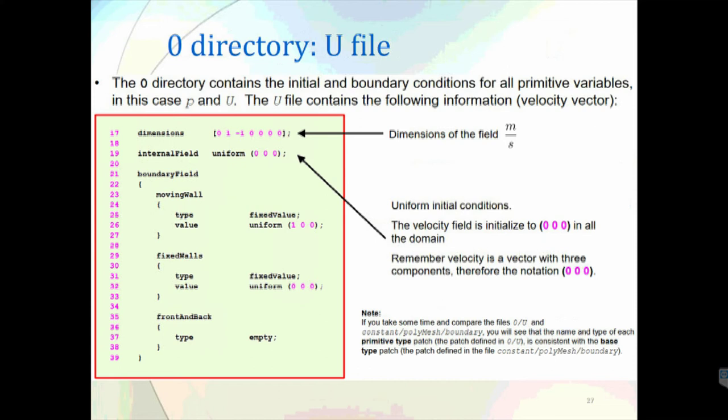Now this is the value of the boundary condition we want to specify. The value of the boundary condition was not specified in the earlier file. The type of boundary condition was specified earlier, but the value is specified here in the initial conditions file in the 0 directory folder. How do we define it?